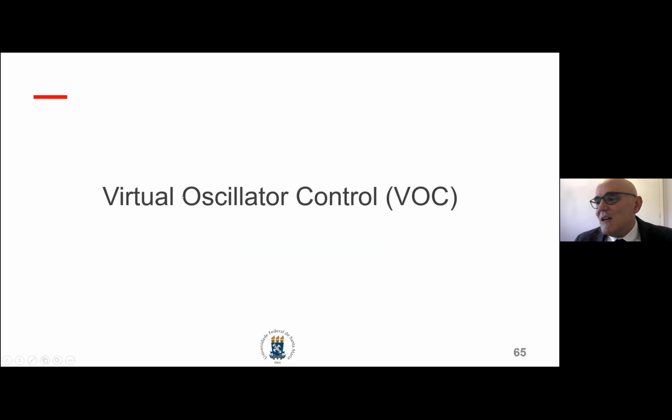the third class is virtual oscillator. Here, the main conceptual difference, in my opinion, is the fact that it's not attached to the legacy system. There is no link of the oscillator with a synchronous generator. The basic idea is to have this property: if you pick two oscillators and couple them, there is a possibility, depending on their parameters, that they will oscillate at the same frequency.